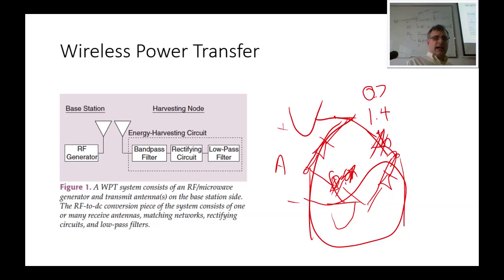And so in this instance, what we have to resort to is a charge pump. Something with multiple stages of diodes and capacitances that store energy, absorb energy, basically charge up capacitors as much as they possibly can in parallel, and then discharge in series, so that we get the kind of output voltage that we need.